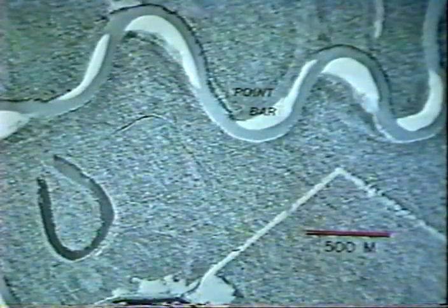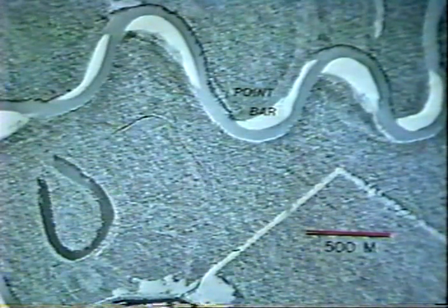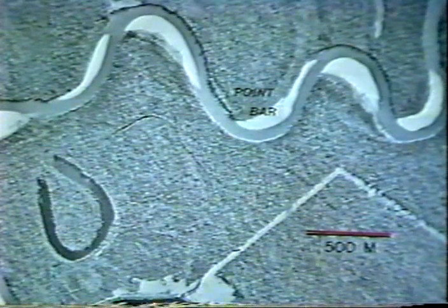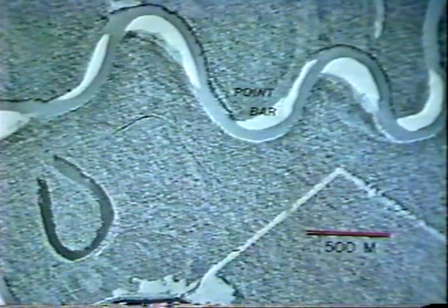The classification just described applies to streams flowing in alluvium. In general, relatively few hydraulic problems are reported at bridges on bedrock channels. A good example of an equal-width point bar stream is the Red Lake River, which has a very slow rate of lateral migration. The Pearl River in Mississippi is a good example of a wide-bend point bar stream, which has a moderate to high rate of lateral migration at the outside of meanders.